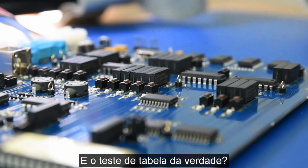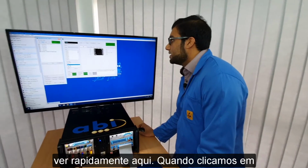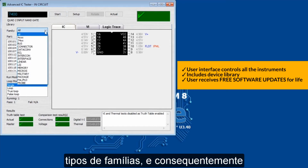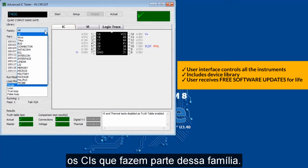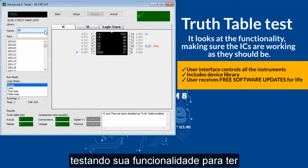And truth table test as well. So the truth table test is done against the System A library. So with the System A software, you have a library full of different ICs from different families. We can have a quick look here. So if I select the family list, you can see a list of all the different families, and obviously if I click on one of these, you'll see all the devices within this particular family. Okay, brilliant. So the test is done against the library. The truth table test basically looking at the functionality, making sure that the IC is working as it should be.